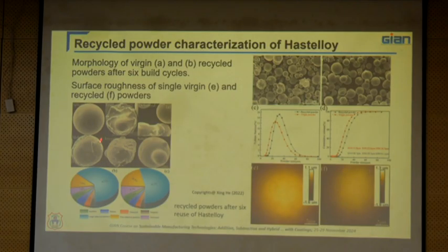And if you see, these are highly spherical powder particles, fractured powder particles, deformed powder particles, irregular, satellites, and as well as melted. There are different sizes and different morphologies of powder particles, right? In these, the original powder particle is E, right? Because it does not fracture, does not deform, and does not lose sphericity.